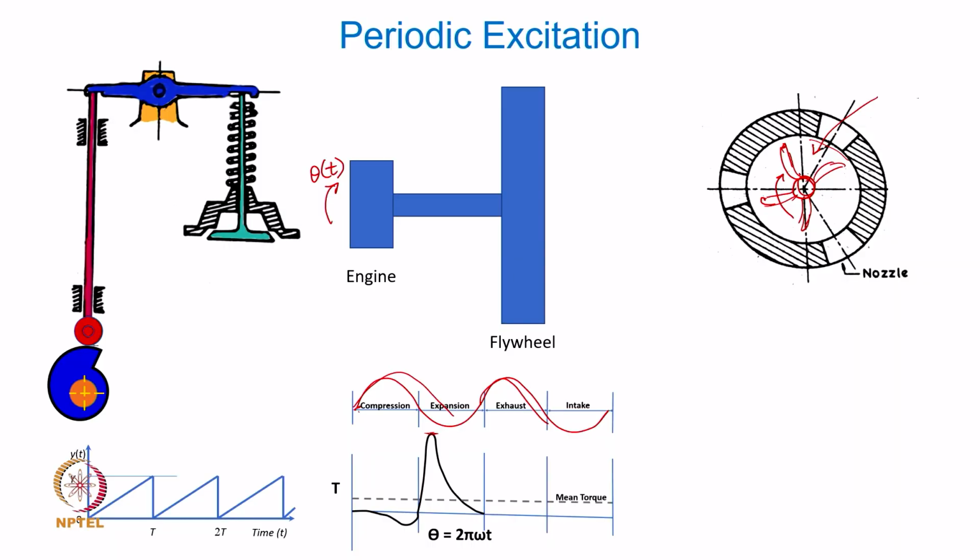Three times, depending upon the number of nozzles. In this case, you see that there are 3 nozzles, equiangularly situated. So now if I consider a blade to be a vibratory system, then this force as a function of time again is no more a harmonic force, isn't it?